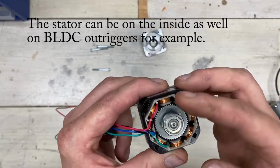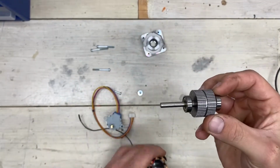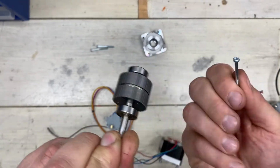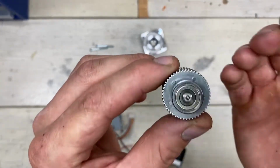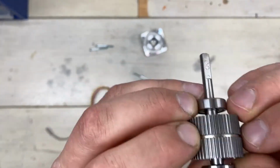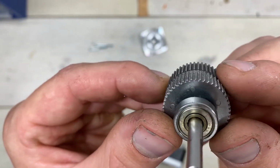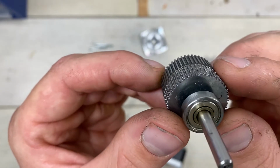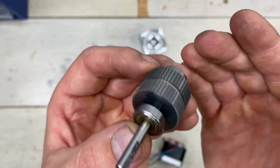And the permanent magnets in this case are on the rotor. And as you can see, it's magnetic, and it is shaped like a sprocket or cogwheel to guide the magnetism to each of these points. And as you can see, the tops of each of these cogs are slightly offset. They are offset by 1.8 degrees to be precise. And if you have read anything about stepper motors, that might ring a bell.